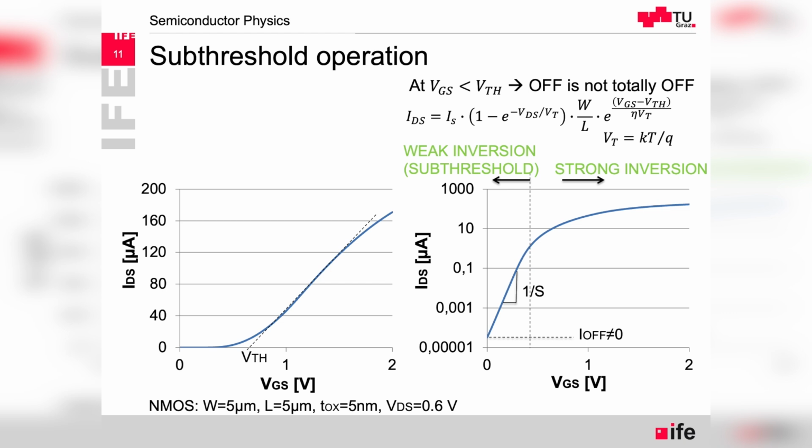If we have a small value of S and a steep subthreshold slope, then the difference in current between fully off and fully on will be huge. We are interested in having high current drive capability when the transistor is fully on, so it will also have a low on resistance. And when it's fully off, we want to have a low leakage current.